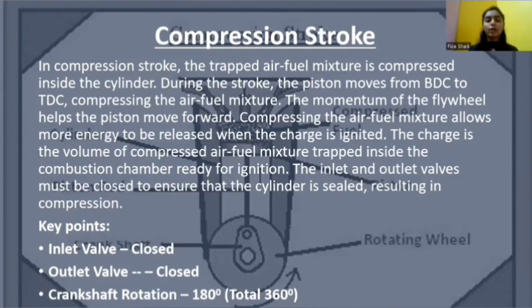The charge is the volume of the compressed air fuel mixture trapped inside the combustion chamber, ready for ignition. The inlet and outlet valves must be closed to ensure that the cylinder is sealed, resulting in compression. Key points to remember in compression stroke are: the inlet valve and the outlet valve both should be closed, and the crankshaft rotation is 180 degrees and the total is 360 degrees.